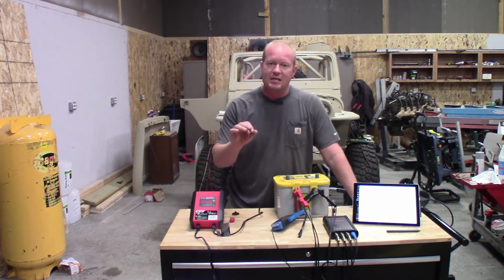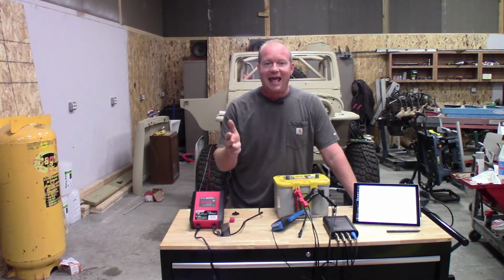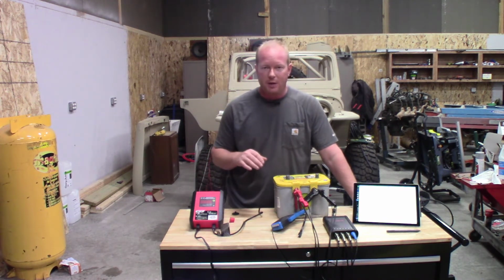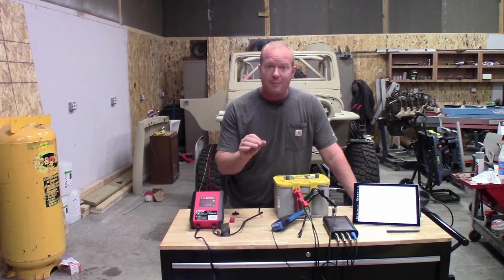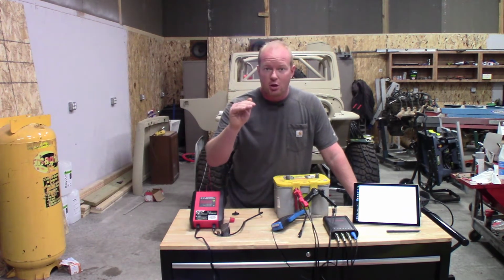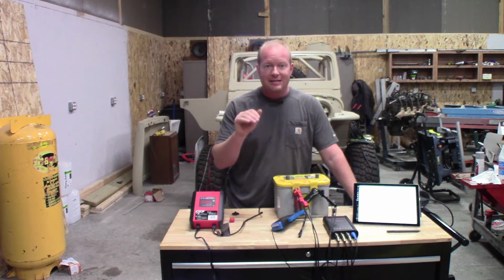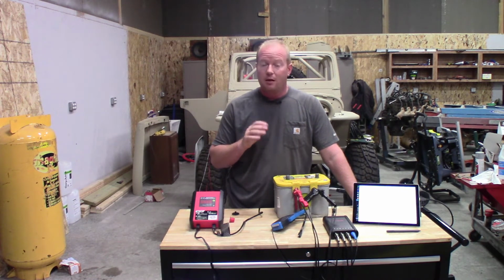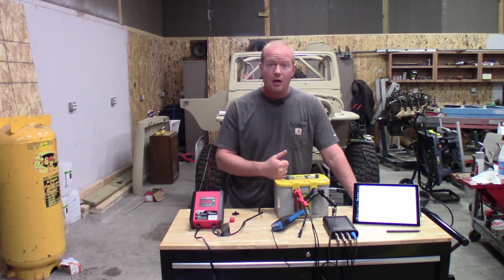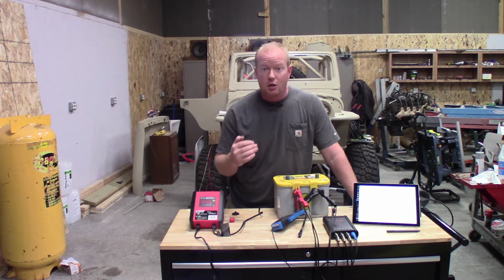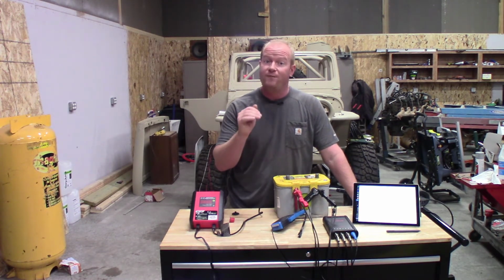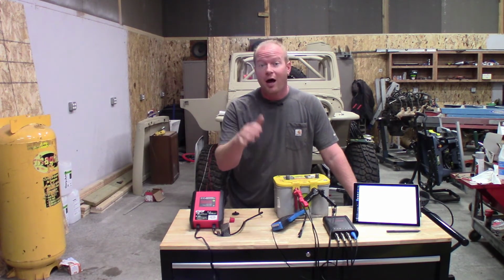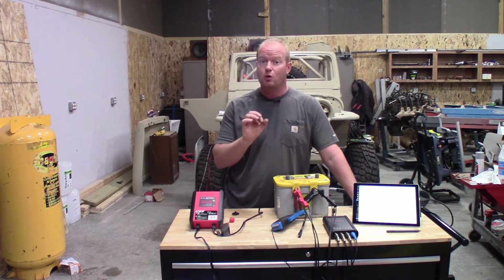I'm going to show you the differences in voltage, amperage, and AC ripple coming out of each individual maintainer, charger, and stable battery supply. One of the things you want to remember when programming is you want to maintain a specific voltage. You don't want it to change, and you have to maintain zero or as little AC ripple as possible. Now, I'm also going to load down the battery to see how the voltage changes during that load, because when we're programming, we can put a very heavy load on that vehicle, sometimes in excess of 70 up to 100 amps on some vehicles. So we want to make sure that we can maintain that.